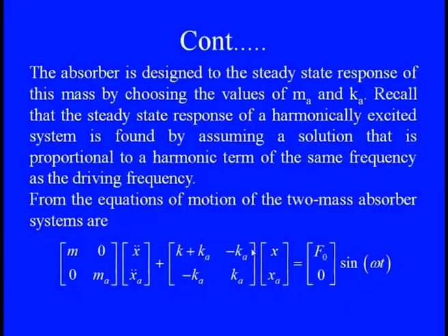With this we can straightaway go to the equation of motion, because we know it is a 2 degrees of freedom system, so the matrix form is featured out. Here m1, m2 is the mass matrix with the inertia forces with acceleration, the restoring forces with the symmetric spring matrix, and whatever force is excited at one mass, say at m1 or m2. Right now we say that at m1 we have the sinusoidal harmonic excitation F0 sin omega t.